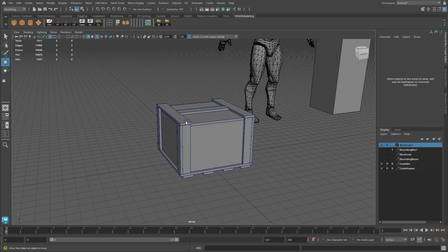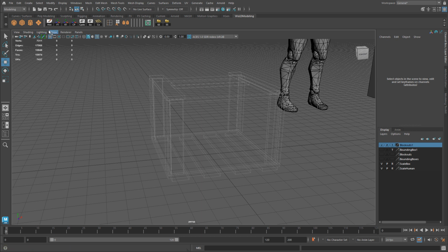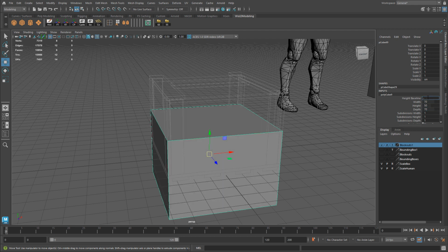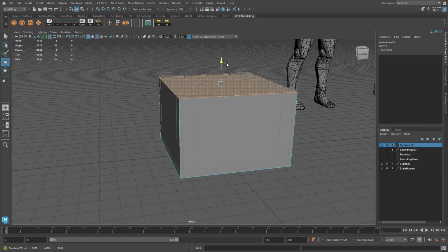We could reuse some of these wooden planks and that would be our starting point for the modeling process, or we could just go ahead and start with brand new ones. This is a simple object, so I'm just going to create new meshes and I know exactly what the size of them needs to be. So I'm going to make sure that I have this on wireframe and let's introduce the overall cube. And I'm just simply going to input width to 70, depth to 70, height to 50, and height baseline -1. Then I'm just going to lower this because I know it needs to come down.